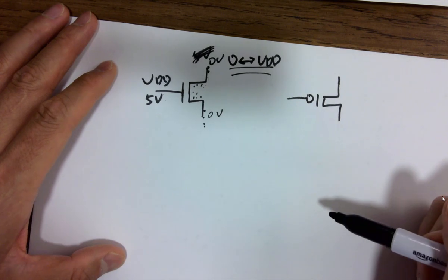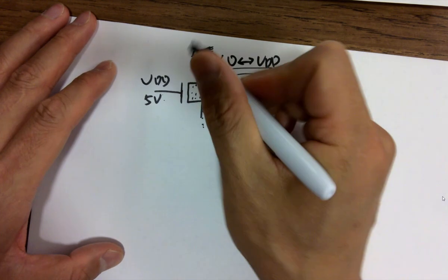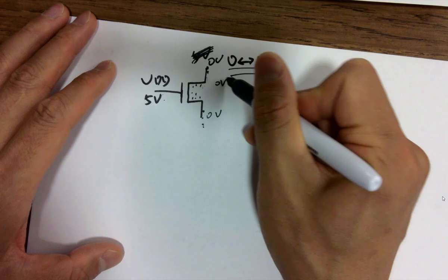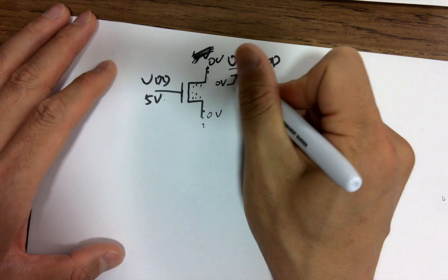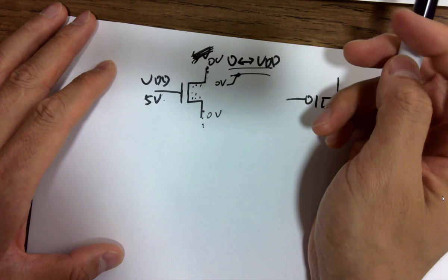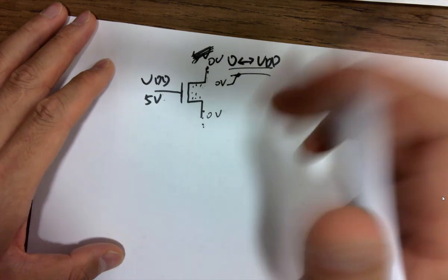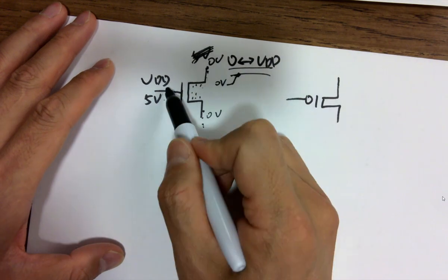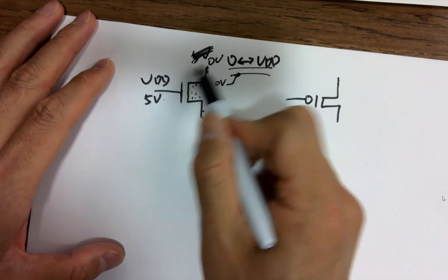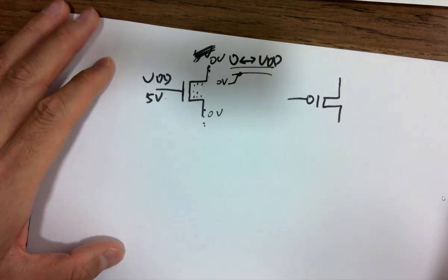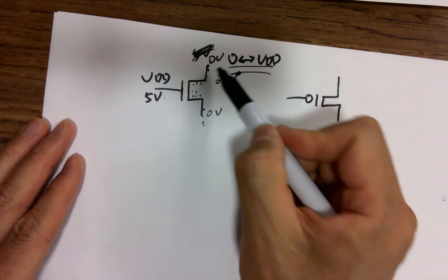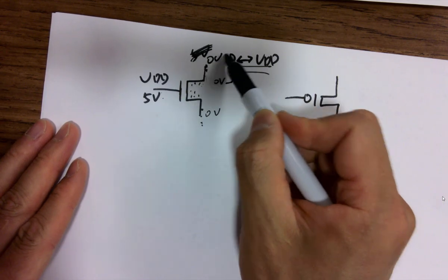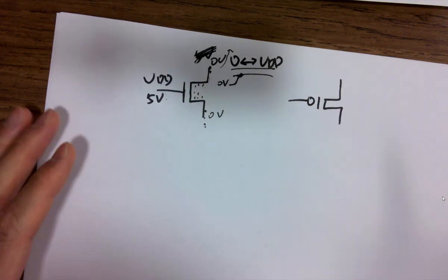No problem. And now let's increase this voltage from 0 volts. Keep going. No problem. Until when? When they're equal? Is it when the gate voltage is equal? Like I said, either one serves as a source or drain. It has to satisfy a VGS of at least VTH. So VGS has to be larger than the threshold voltage. So if this one starts going up, until when are you seeing problems?